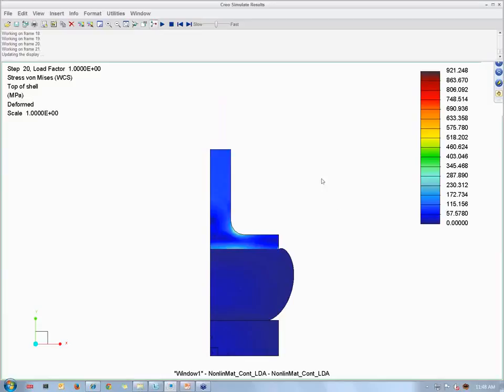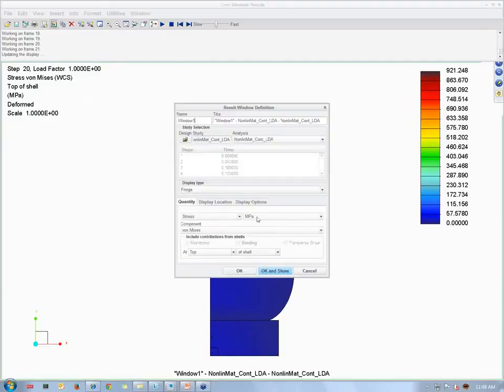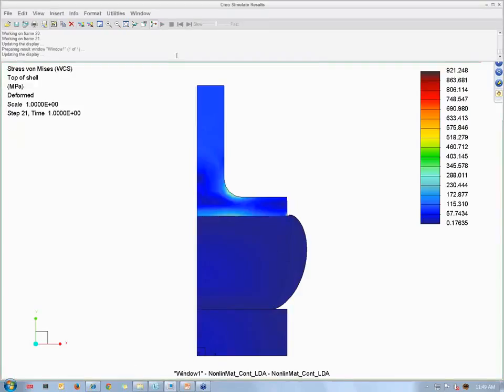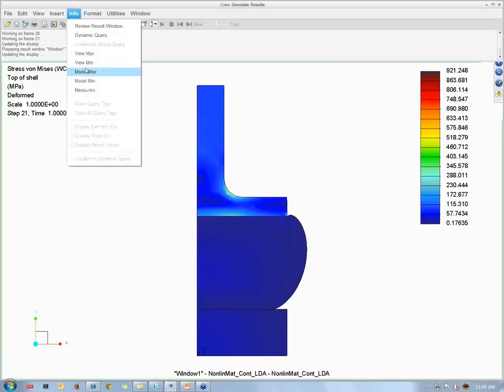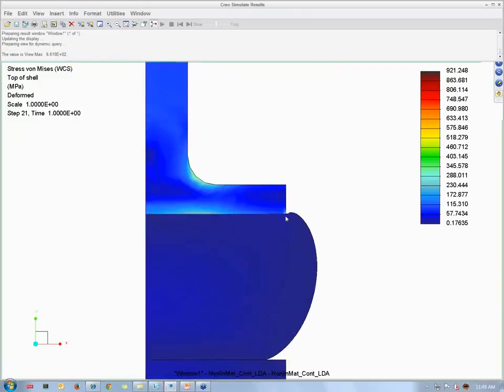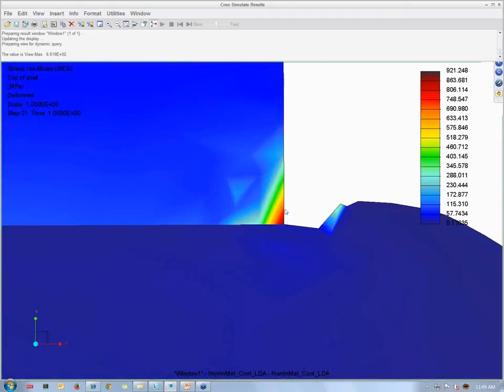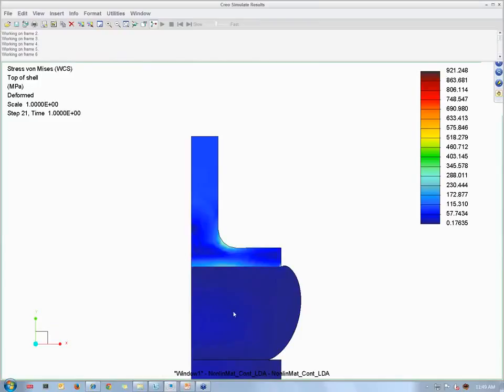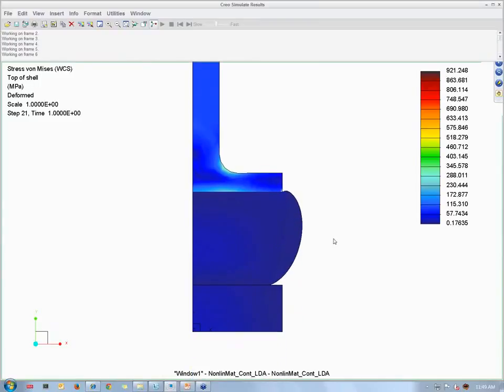Right now, this is showing me a max stress, and again, we could go view the max stress, not in animation. Let me go turn off animation. I want to view the max. We could go view the max, and we see the max is right at this corner, where we're going to have a high stress. We're going to also see some stress values here. But we see very little stress in the rubber stopper just because we're compressing it.